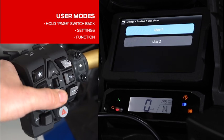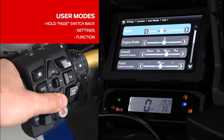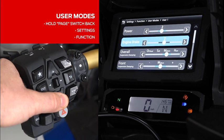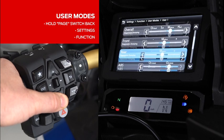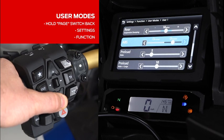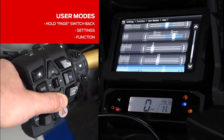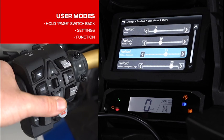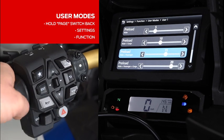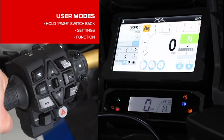You can select User 1 or 2, and there you see the options of what you can adjust. Power, engine brake. For the adventure sports model, you can adjust suspension, as well as the ABS preload for the adventure sports adjustable suspension model. All these functions will be saved within that individual user mode. Simply return back by holding the page button down one time, and you're back at the main menu.